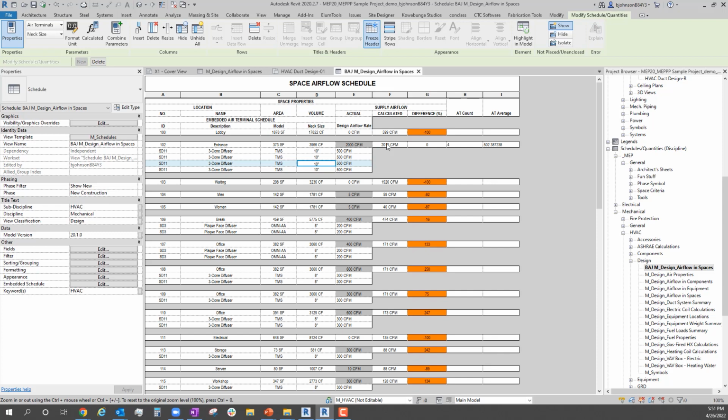If that's not the same in Trane Trace or HAP or something like that, Trace 3D Plus, you could compare those values to those systems, see what you get, and if you're within 1 or 2%, I would say we're pretty accurate. If it's 10% off, 20% off, and it's always in the same direction, always plus 20%, then I'd buffer up to like 520, 525, something like that to give it the CFM that it truly needs, and then not really care about my difference. Or I'd set my difference conditional format to not 5%, but like 20% or something like that.